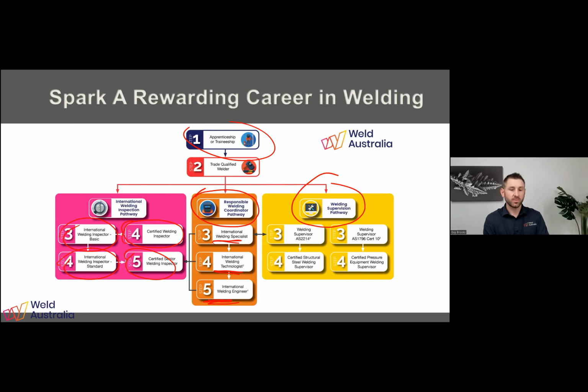Right? A welding supervisor is someone who works with the inspector. Sometimes they're also an inspector a lot of the time, but they never have the same role. What happens is they're the person who goes through and qualifies the procedures. So they're the person who writes maybe a PQR, and then writes a WPS.